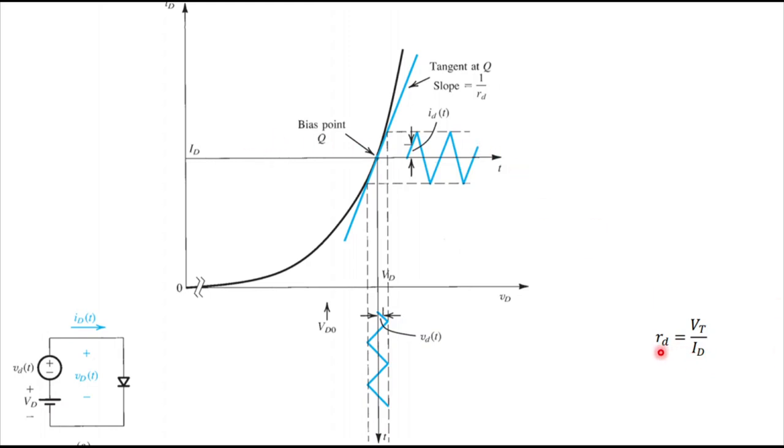Okay, so for this small signal that is riding on top of a large average signal, we can assume that the diode just behaves like a resistor. And this model is called the small signal equivalent model of our circuit. And in this case, the diode is just replaced by a resistor of Rd.